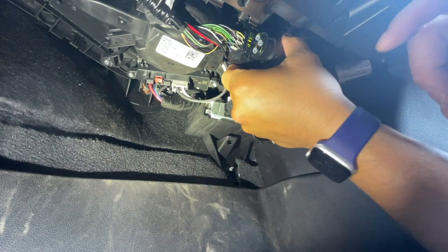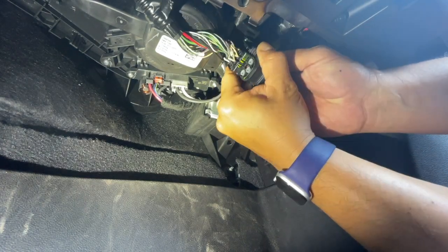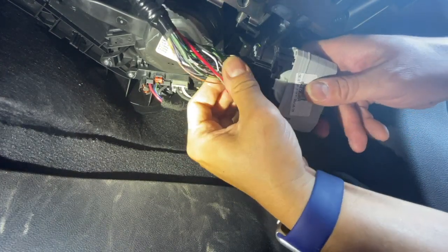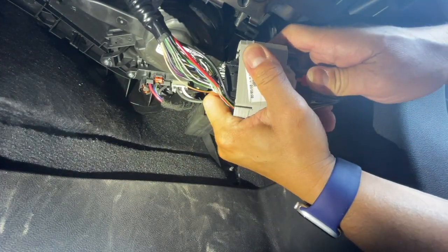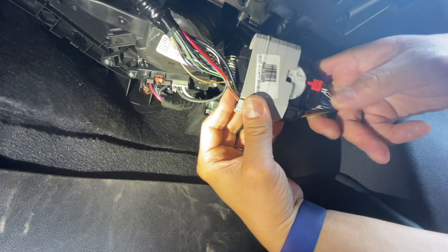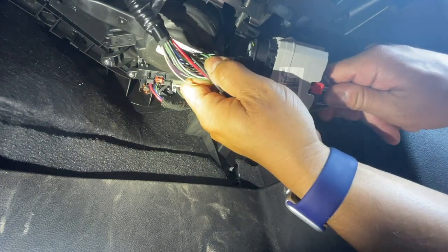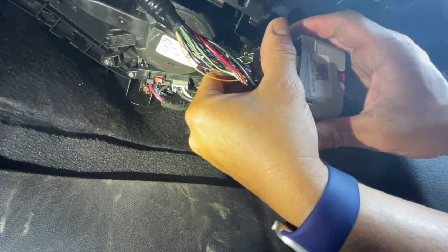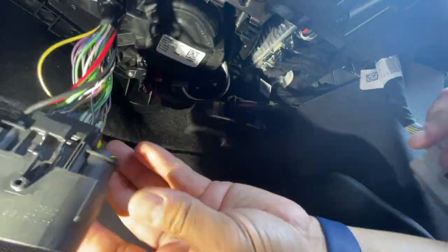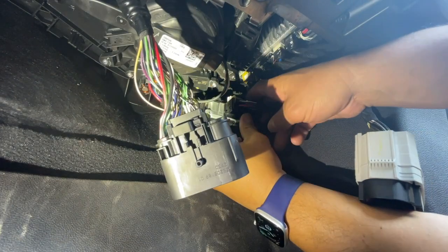This side is actually held on by a retaining clip, and so I was able to just carefully pry it off just like that. All right, so show that to you again. So this is in the locked position. Release the CPA, slide the gray connector back, and then disconnect. Now that's out of the way, we have access to remove the inverter module.